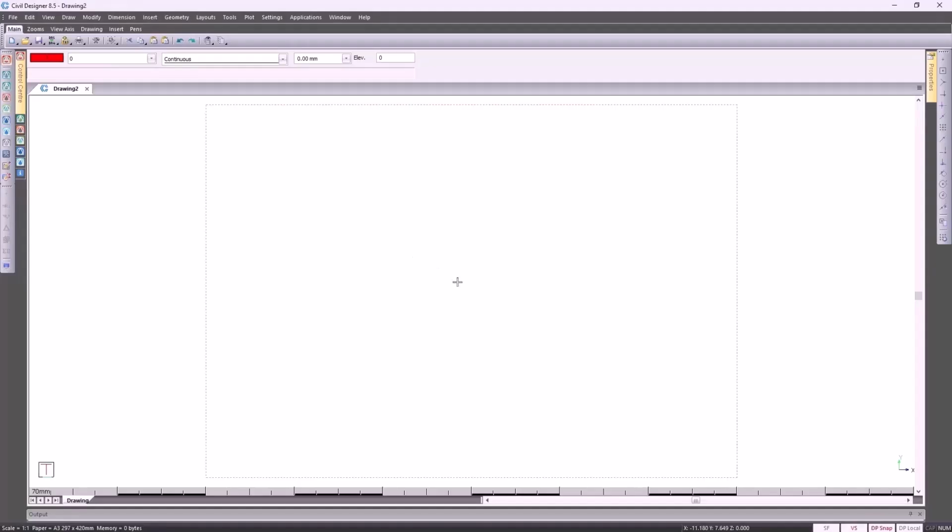It's vitally important that you create your project correctly, because that serves as a foundation to the rest of your design. And a lot of times you might just be using the default values. I'm going to show you how it's done correctly. I'm going to go to my survey mode. I'm going to go to File and select Project Settings.